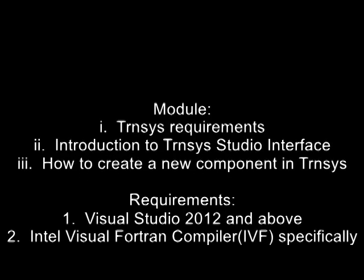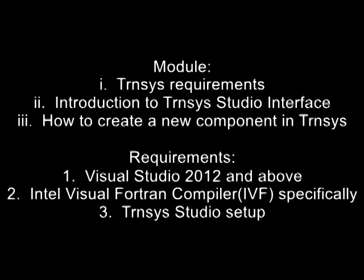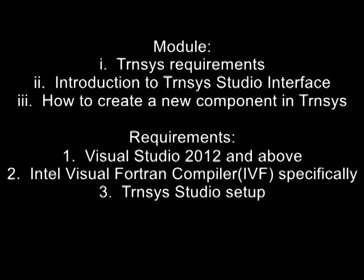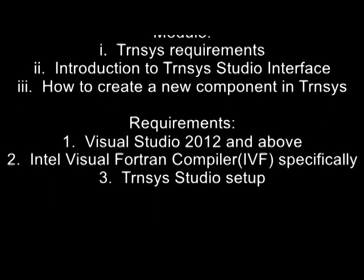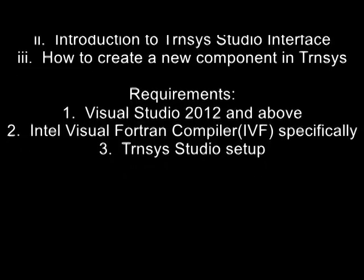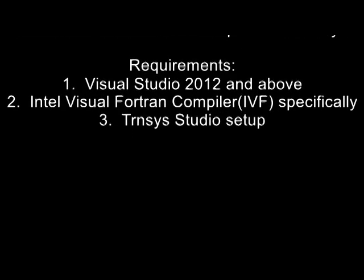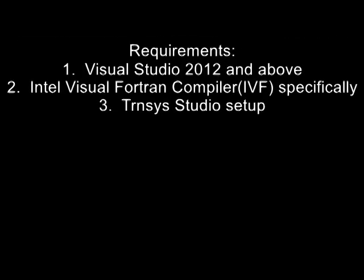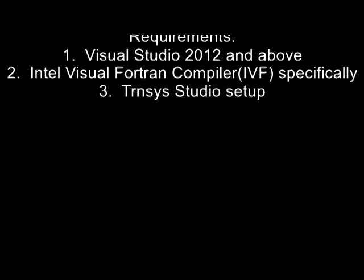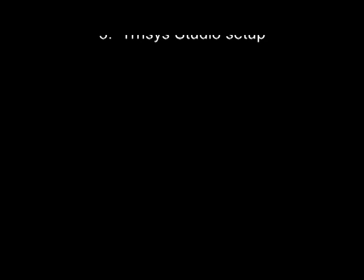On the requirements of Trnsys, Trnsys Studio is a complete studio that yet requires other third-party softwares for various manipulations in a simulation project. The important third-party softwares to have are 1. Visual Basic 2012 upward, 2. Intel Visual Fortran compiler specifically, and of course Trnsys Studio. Without this, it is impossible to create a functional component within Trnsys.